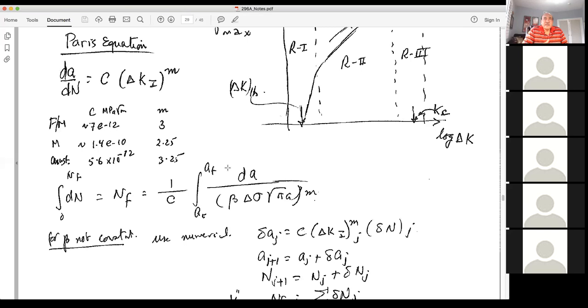So if we have non-destructive evaluation, for example, an acoustic method, then we can detect a minimum crack size, let's say on the order of 10 mils, 10 thousandths of an inch. And that could be done on a massive scale when they produce and manufacture connecting rods, and they have to inspect acoustically every one of them to see if there's any crack that is above that value.